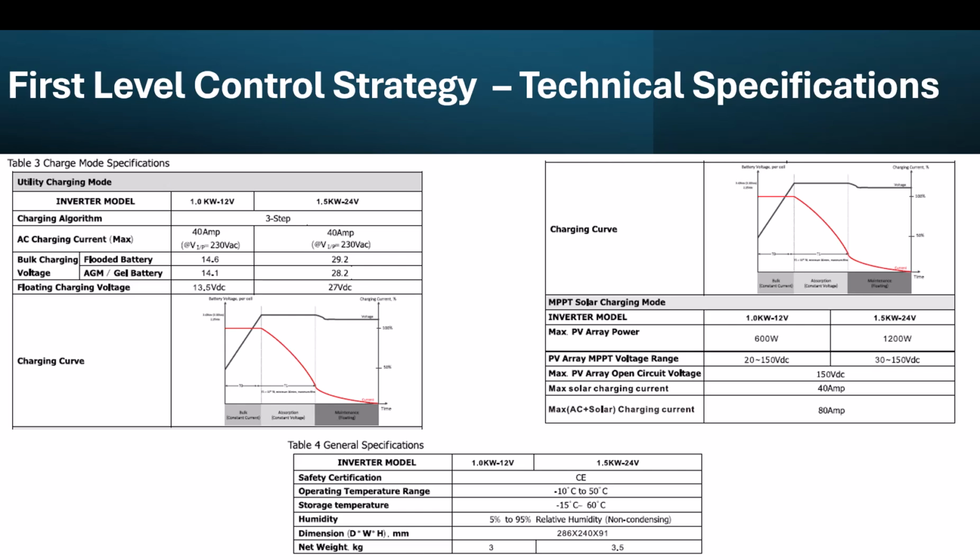But also, one thing that is worth noting is that almost all the inverters will also have a short time rating. For instance, how much can it push if you have loads like electric motors or motorized loads connected to your system. So this gives you a benchmark.